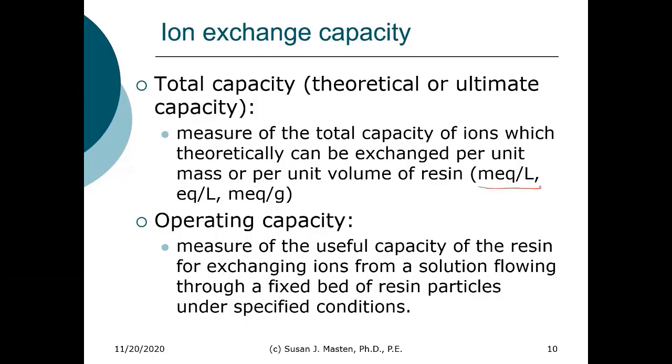And this is typically in milliequivalents, and that's milliequivalents of whatever ion you're exchanging. And this is per liter of resin, or in this case, grams of resin. So this is milliequivalents of the exchange ion per liter volume or mass of the resin.